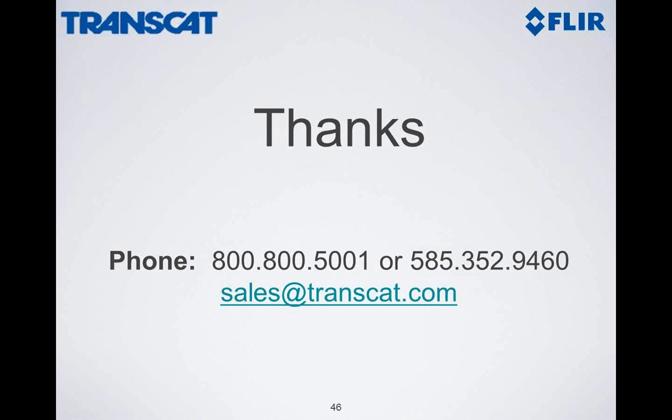That's a very good and basic question, Nicole. It really depends on the size of your target and in relationship to the number of pixels. Generally, a camera that has 76,800 pixels can accurately measure a 1-inch target from about 20 feet away. If you cut the number of pixels in half, you generally can cut the distance in half. If you are twice as far away, then you would have to increase the number of pixels, let's say up to 307,000 pixels to get that same 1-inch target.